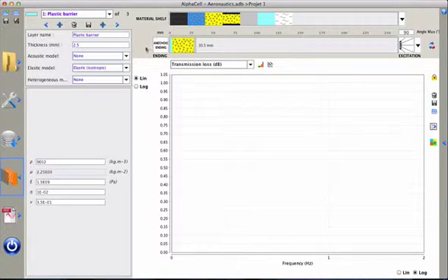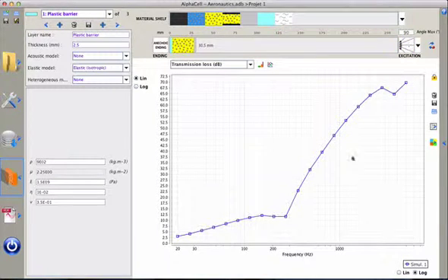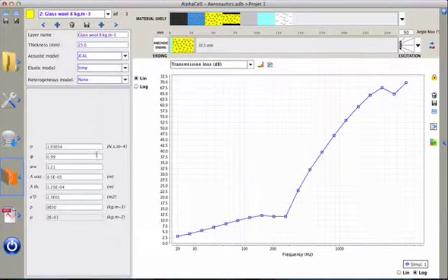So on one side we have an anechoic ending, and on the other side we have the excitation, a diffuse sound field. And I click on the button and we get the result of the sound transmission loss for this configuration computed with the transfer matrix method. And it's quite easy and quick to see the influence of one parameter. For example, the influence of the open porosity of the glass wool on the sound transmission loss of the wall system.